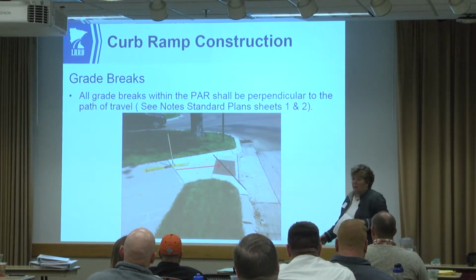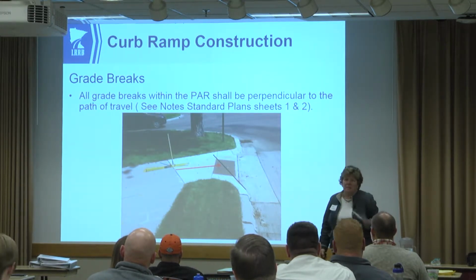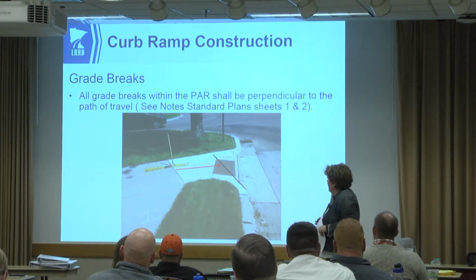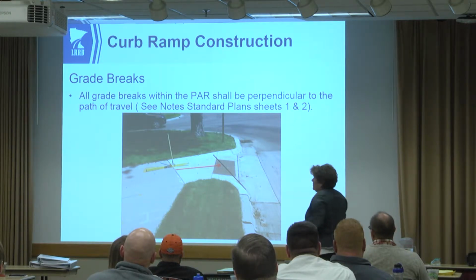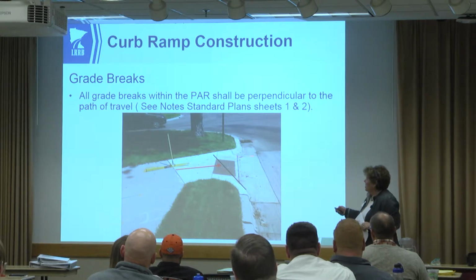It looks like they just followed their curb lines and extended their sidewalk joints on through. Yeah, they did. What you're left with here is this little triangular piece. I don't like that. Every curb is different. All we're saying is make sure that you go through the jointing layout with the contractor. What do you think, right or wrong? It's wrong, right? Because we already talked about it.